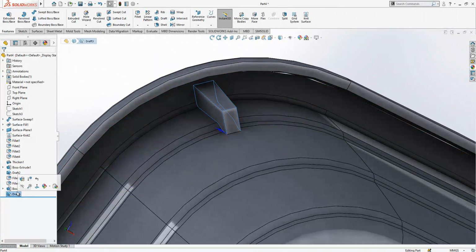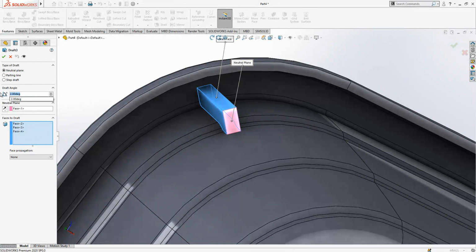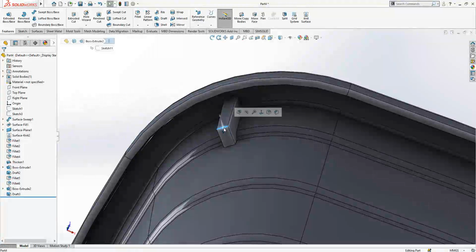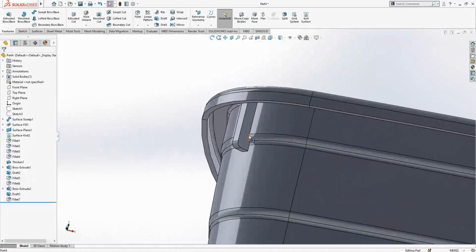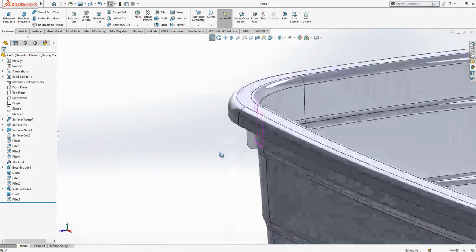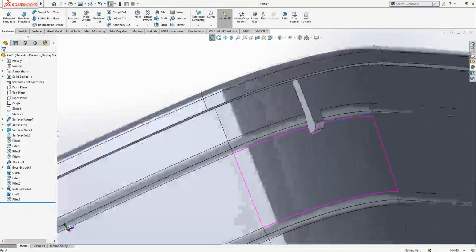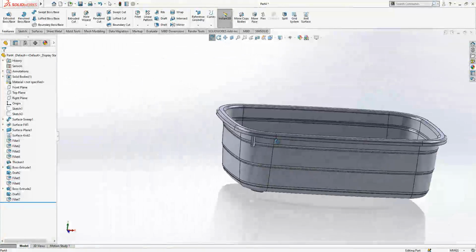When you give 2-degree, it is looking very big compared to the rest. There is a critical thickness in the materials that you could give. That's a very important value. If you are not noticing that, you will not have nice properties after injection, because then there will be deforming because of the thickness in this area. It will cool down slowly compared to the normal areas, and then you will have problems. These are important things that you should consider.